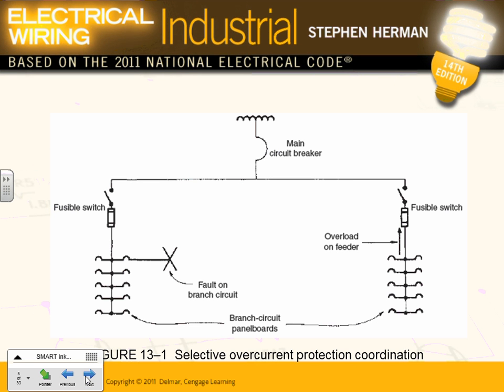Okay, so that's selective overcurrent protection device. When we say selective overcurrent protection device, guys, if you have a short circuit right here or a ground fault right in this location, the one that's going to trip is this one, not this one, not this one. Okay? Does that make sense, guys? You have a short circuit right in this area. The one that's going to trip is this particular circuit breaker, that 25 amp or 15 amp circuit breaker. Any comments, any questions?